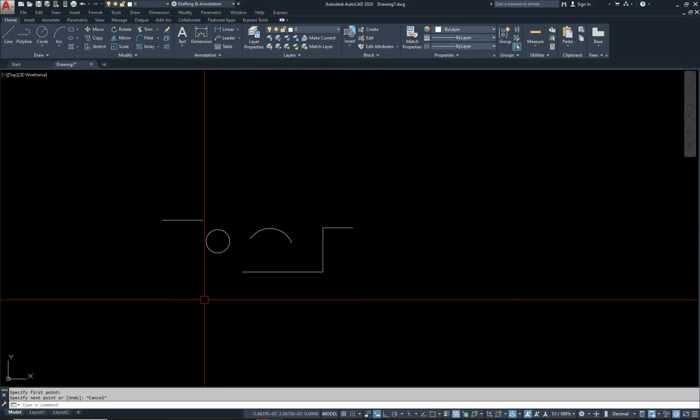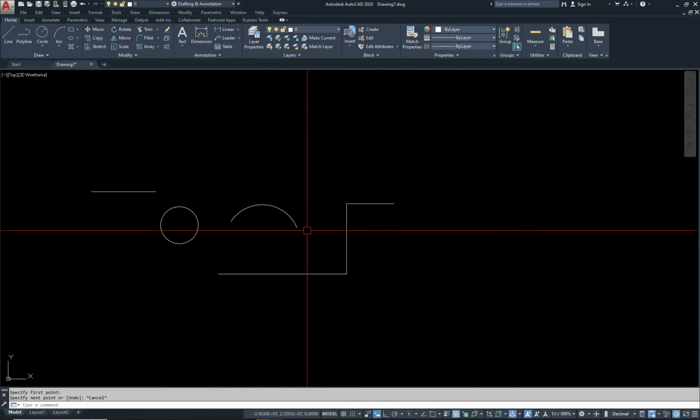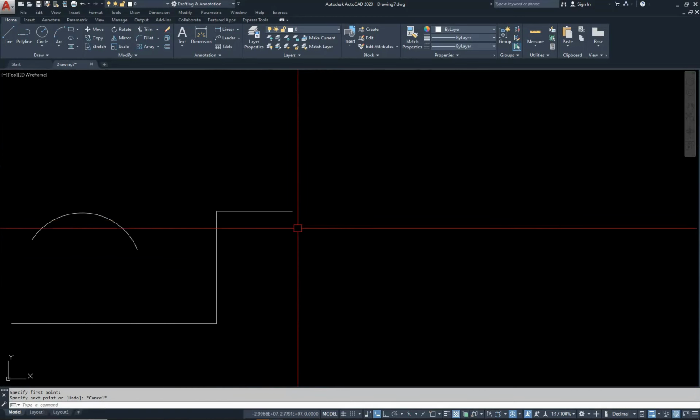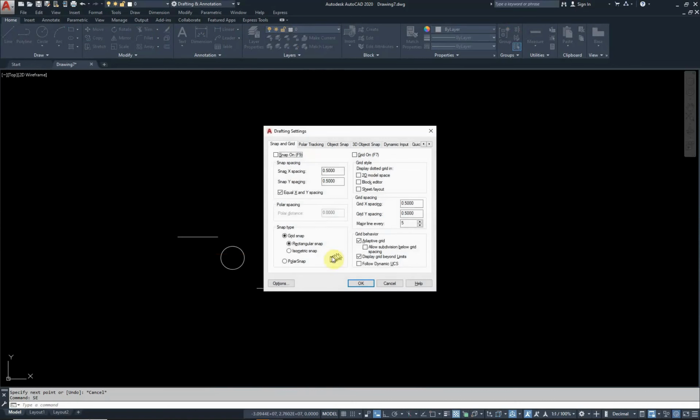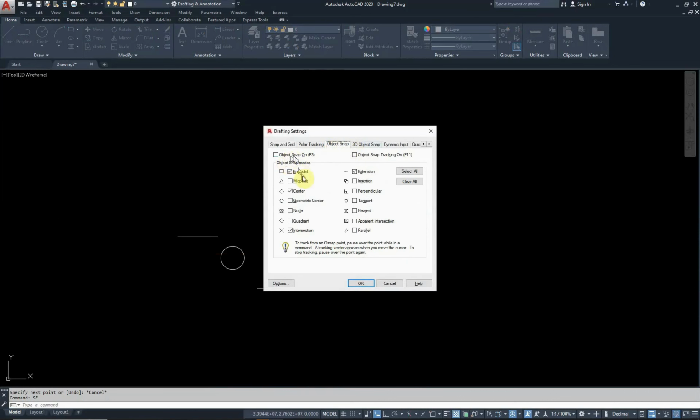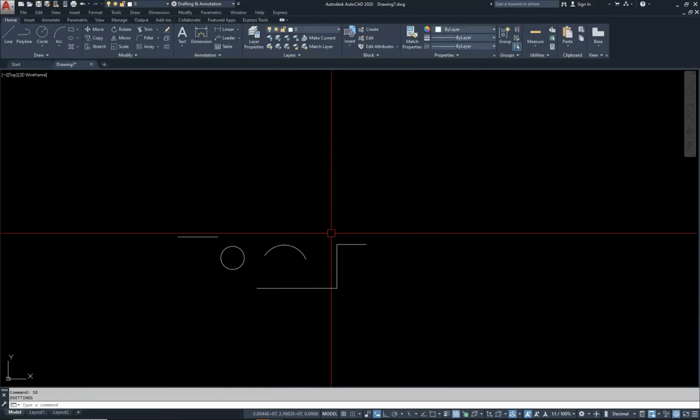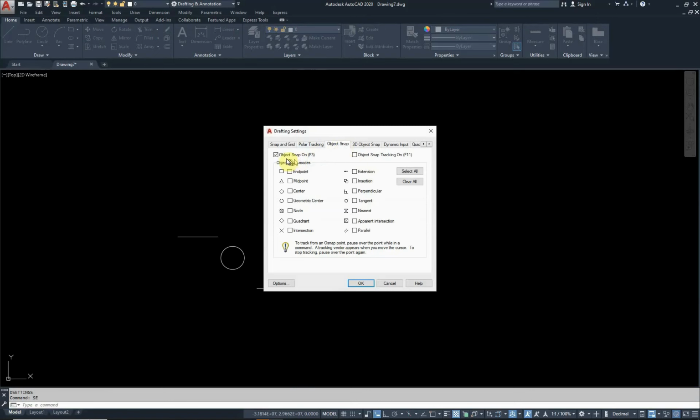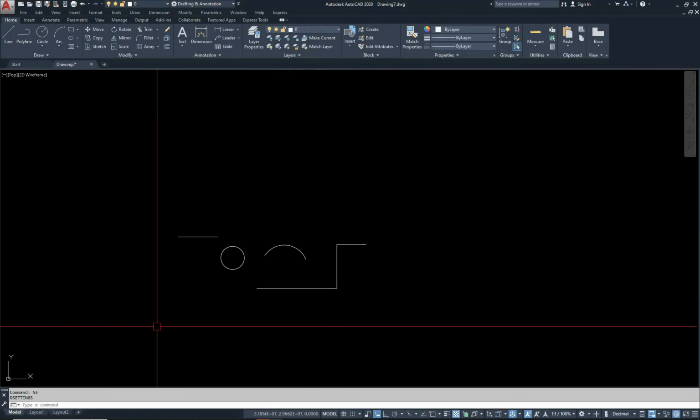Okay. So now again we will continue with our discussion regarding the Osnap settings. I hit SE and here I see this is my Osnap, which is off, unchecked. I will just check it and I will uncheck all these options from here. So it is showing that there is a button F3. AutoCAD is saying, no need to type SE settings and come into object snap and then turn it on from here or off from here. Simply press the F3 button.